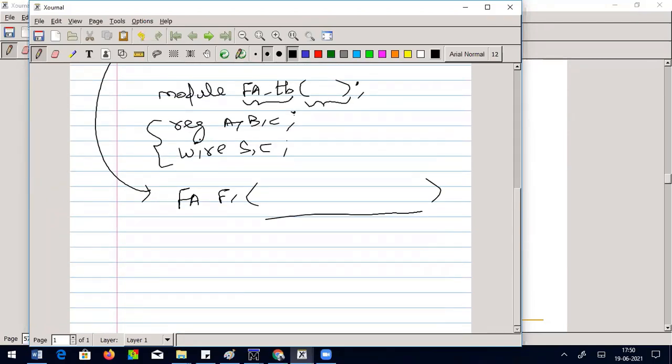You have defined one module, defined what is reg, what is wire. You have called which circuit or which module to be tested. Now you have invoked everything. What next? You need to feed the value. What is the way to do that? Initial. Use an initial command. Why initial command? The reason for using an initial command is anything inside an initial command will get executed only once. So make sure, say something like this.